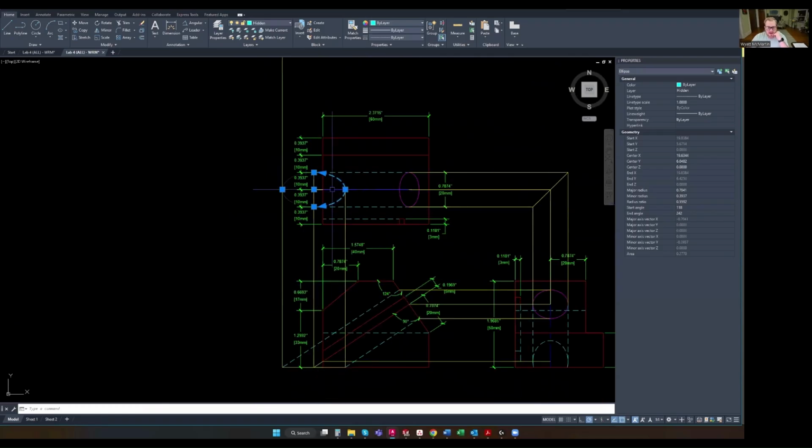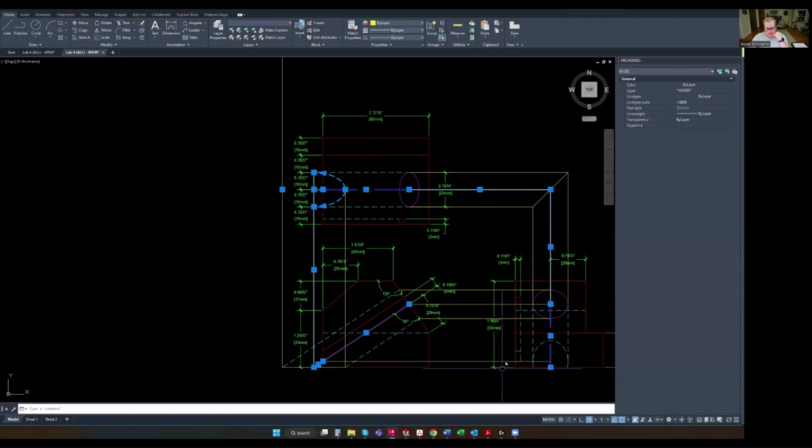So we can see we have a center line, our center line, our center line, just like that, coming all the way through here. That center line, in this view, does not project. It just was where the circle comes out at the bottom of the part. So you can start to see how this projection actually works.